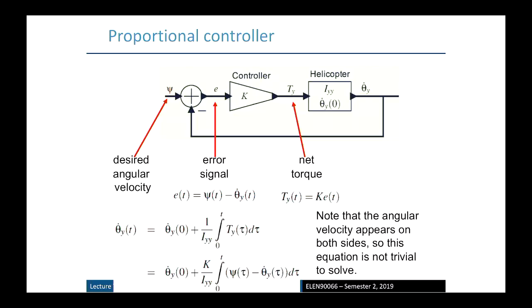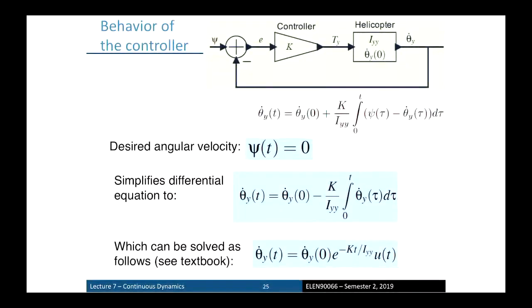So here's the actor model of the controller. Once again, you could go and drop this in Simulink in MATLAB in a few blocks. The helicopter, you zoom in, it's composed of two elements, the proportional one and the integrator, and you've got a controller on the outer level, which is a proportional one, and then a summation where you're subtracting something.